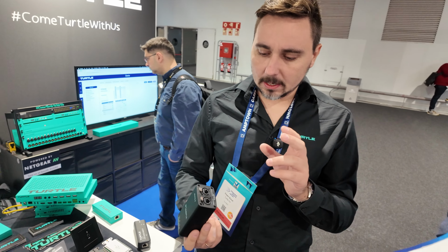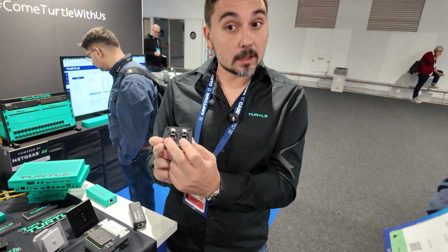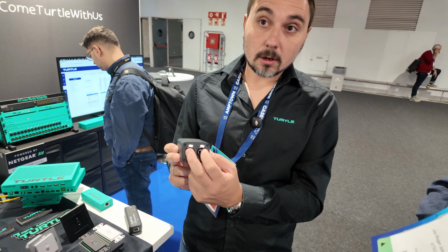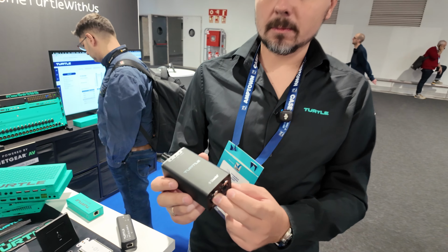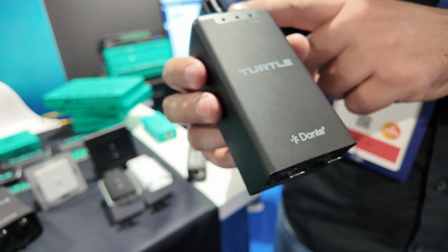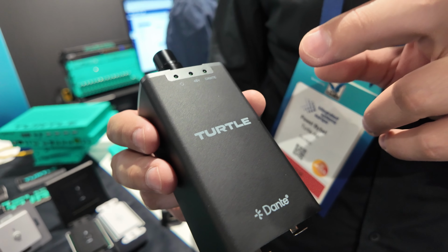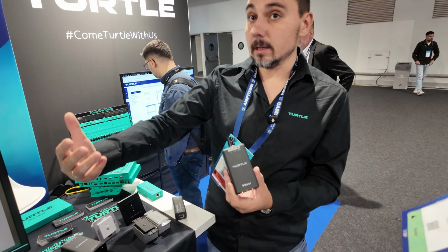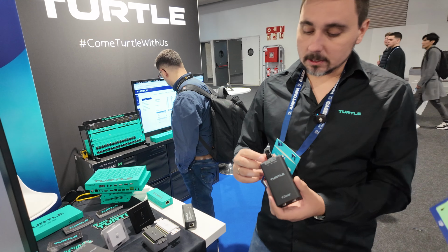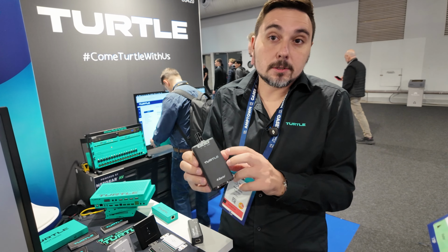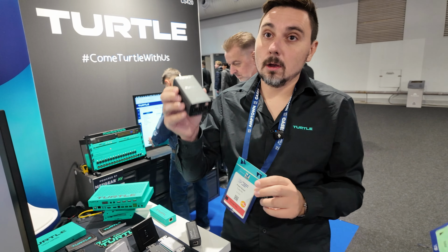So this guy is PoE powered with PoE redundancy, so you got two PoE circuits and Dante redundancy, locking intercom connectors. So you can power it from a switch. It provides you 48 volt phantom power for your microphone. It comes with API support and web interface, so you can manage your mic preamp remotely through API or through the web-based interface. It also has built-in DSP capabilities, so you can process your audio on the mic and send it across your Dante networks.